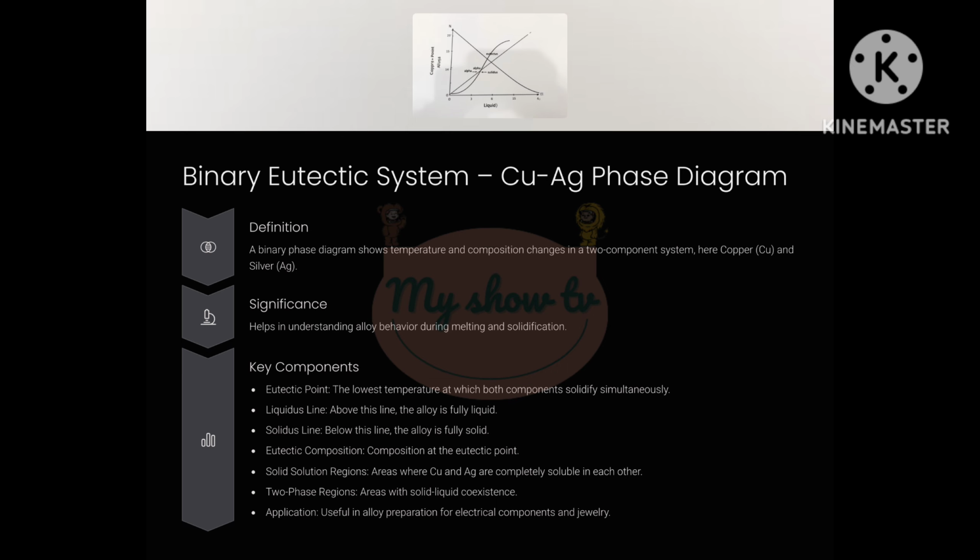Slide 3. Binary eutectic system, Cu-Ag phase diagram. Now, let's move to a more complex system, the binary eutectic system using copper, Cu, and silver, Ag. A binary system involves two components, making the phase diagram more complex but also more useful in alloy design and metallurgy. What is a binary eutectic system? A binary eutectic system shows how the temperature and composition of two components affect the phases present. In our case, we are dealing with copper and silver.